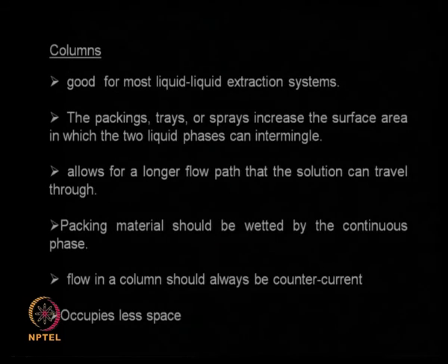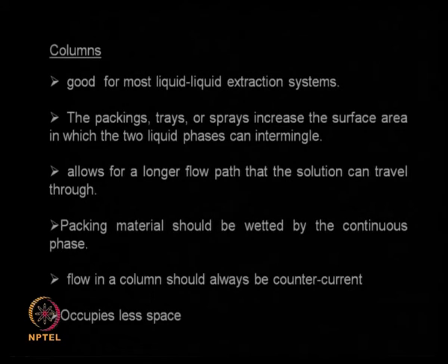Actually, columns are tall structures where you are bringing both your solvent and the heavies either in co-current or counter current fashion, they get mixed thoroughly because you will have trays or you will have packing inside the column. So during those mixing stages inside the column, the partition of the solute takes place. So columns are very good, they occupy less space. I can have many stages, I can put in many separators inside the column in the form of a tray, and each portion is almost like an ideal stage. So it is very good for liquid extraction.